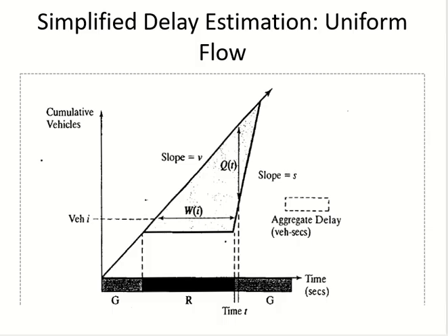This time the car has crossed the signal. Approach delay will be when the car regains its speed. It has crossed the intersection, but it doesn't mean it's going at the same speed at which it came. Maybe it reached the speed, we don't know.